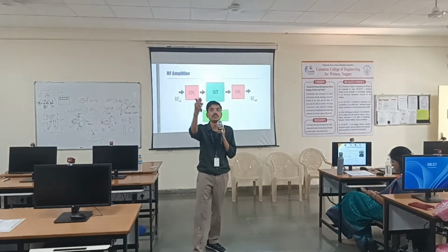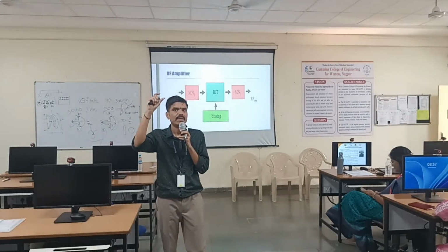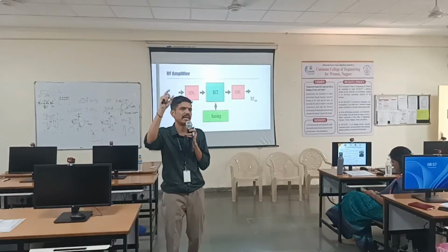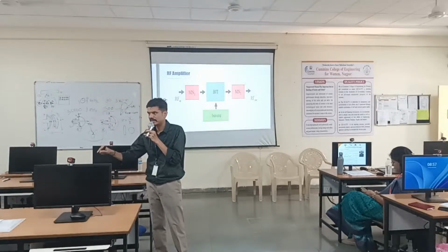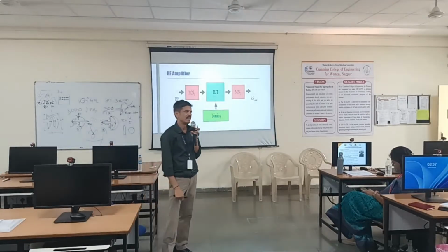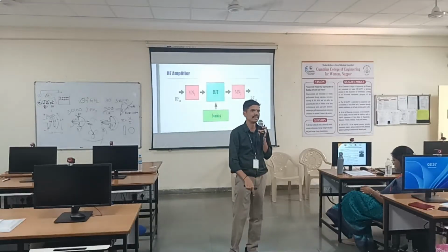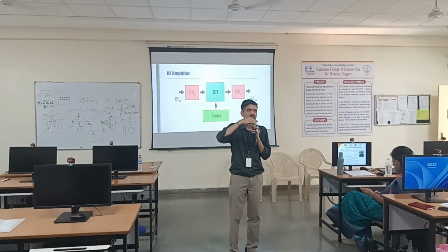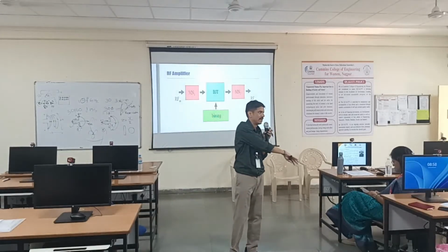I have given you two substrates, sir. One whose dielectric height is 2 mm and number two, dielectric height is 10 mm. Which one will you choose and why for antenna design? Answer is, I will choose the second one whose thickness is 10 mm, and justification is because fringing fields will come out of those transmission lines and lie on your ground plane.